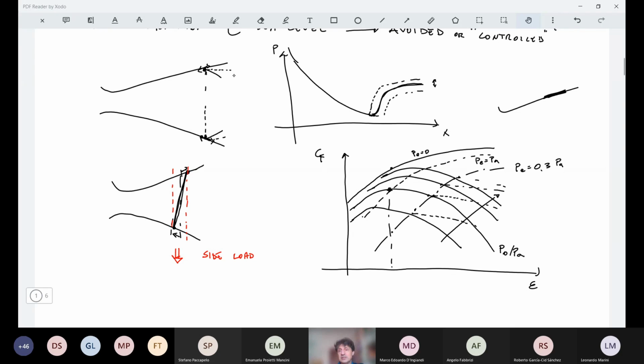What you do is that you assign a given value of total pressure, you find an adaptation altitude, and then you change your ambient pressure during trajectory. So typically what we are considering here is a given epsilon. Let's say this one. This is a given geometry.